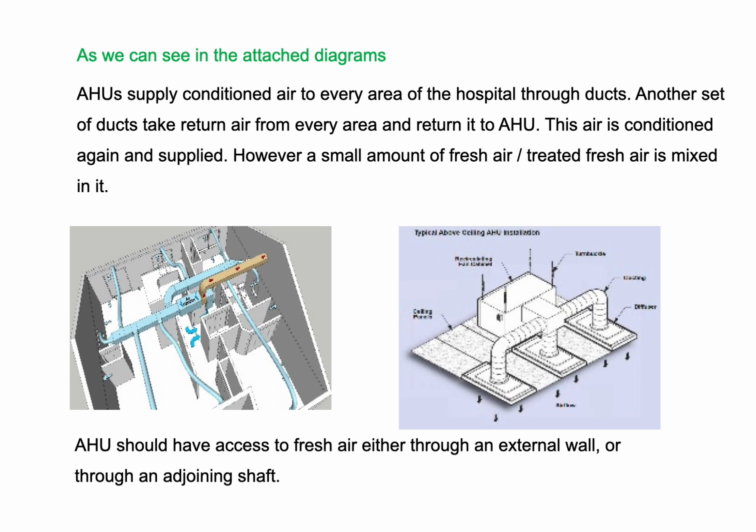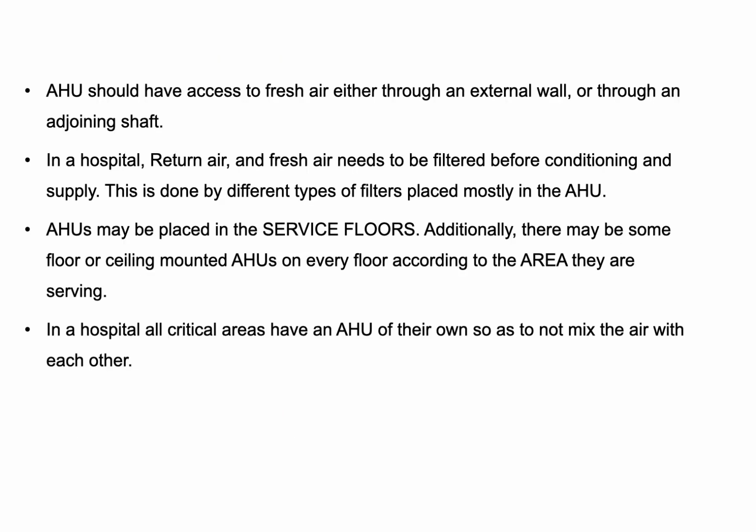However, a small amount of fresh air or treated fresh air is mixed in it. Now, how much fresh air is to be induced or how many air changes per hour is different from regular buildings, and in hospitals it is designed as per ASHRAE 170. The air changes per hour is different for each type of area within a hospital also. An AHU should have access to fresh air either through an external wall or through an adjoining shaft.